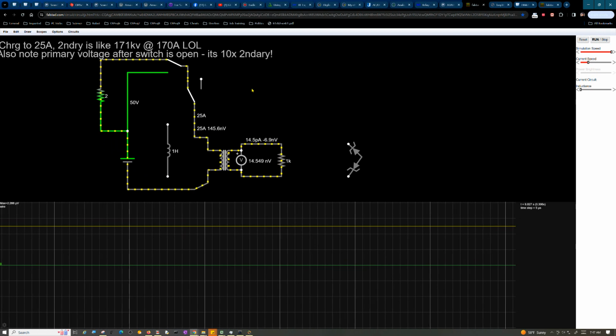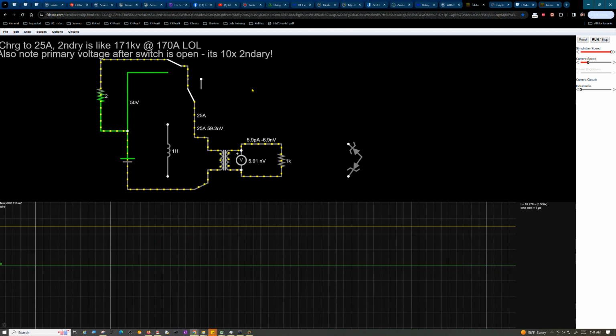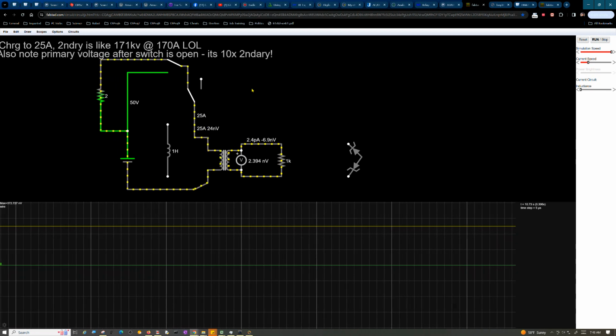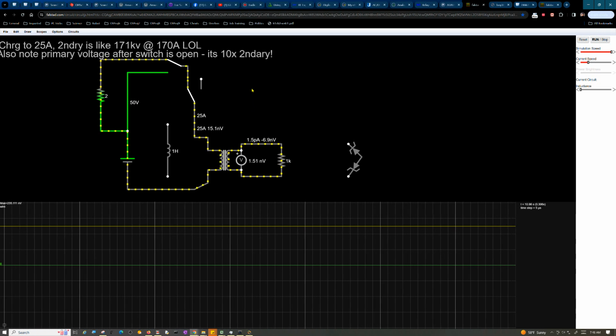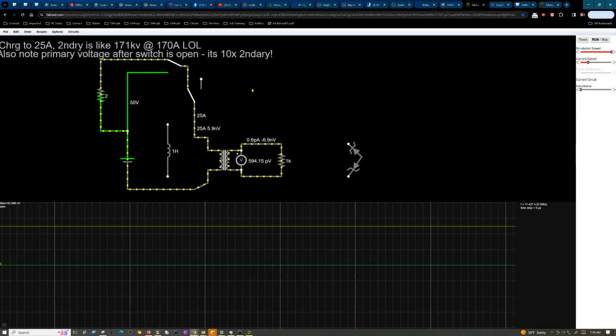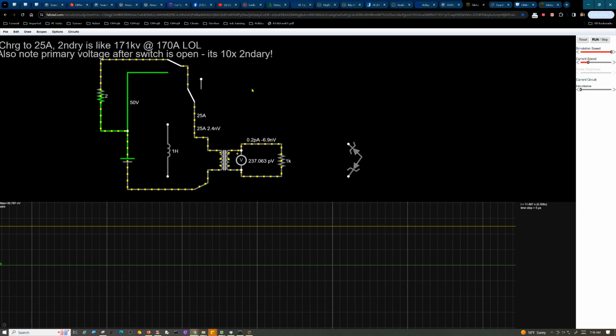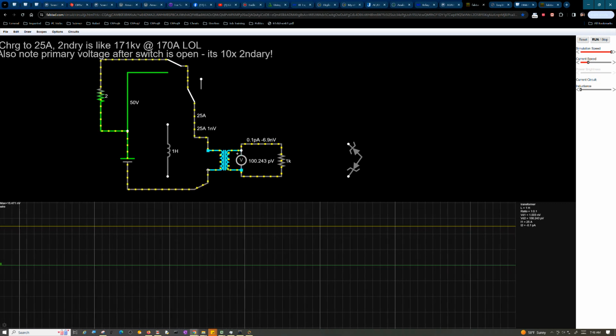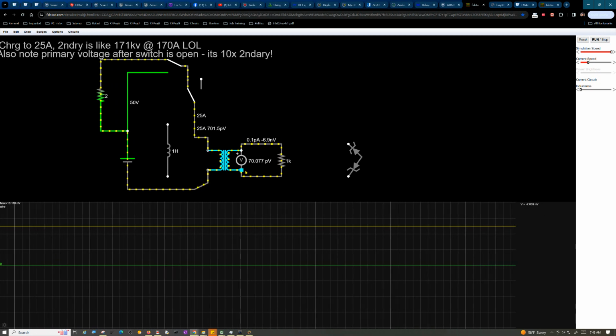In a single inductor, by all appearances that is what it's doing. But in theory, it doesn't want its flux to change. As long as you've got a current flowing through it, like a DC current like we have now, it should be happy-go-lucky. But once you try to remove that voltage, it doesn't like that, so it tries to maintain its current. It flips its polarity to do it, but it's really trying to maintain its field. My question was, well, this is a transformer, right? So wouldn't it try to discharge through the secondary if you had a secondary load on it? And the answer is yes.